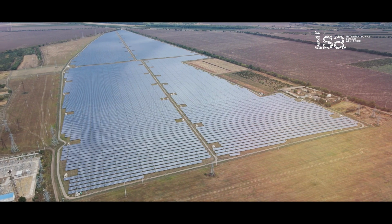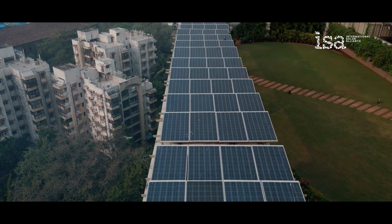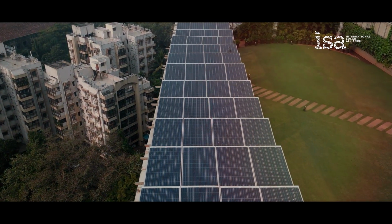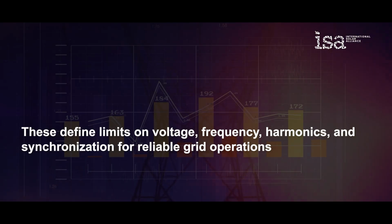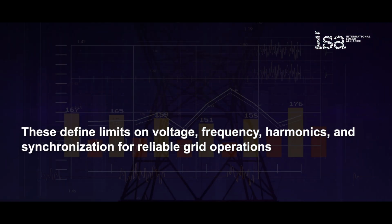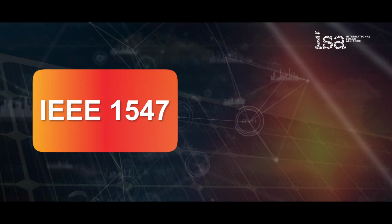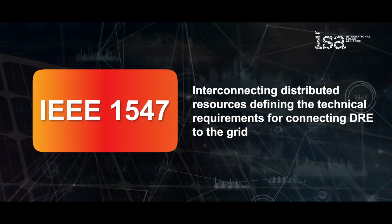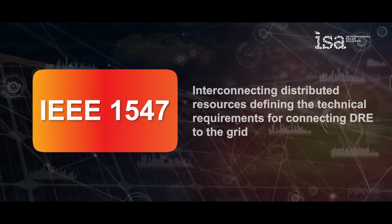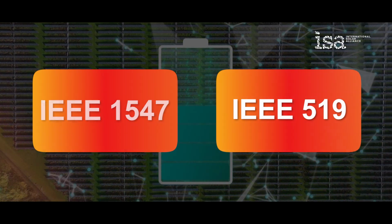Grid integration requires strict adherence to international and national standards, such as IEEE 1547 and IEEE 519, to ensure safety and performance. These define limits on voltage, frequency, harmonics, and synchronization for reliable grid operations. IEEE 1547, Guidelines for Interconnecting Distributed Resources, defines the technical requirements for connecting DRE to the grid. IEEE 519, Harmonic Control Standards for Clean Power.